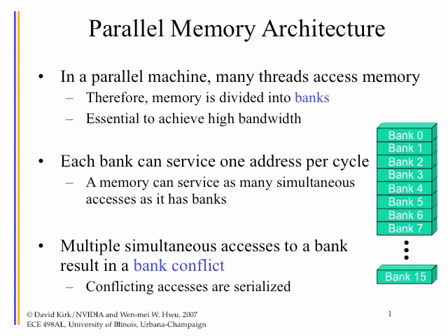You don't need to look at all the bits, you only need to look at some bits. And you can quickly figure out that 2 of them are going to the same bank, or 4 of them, or 8 of them. Once you figure it out, you stop the processor, and then you start to crank out those data values, taking however many clock cycles it takes to get the data out of these banks. Then you give all the values to the processors and you resume execution.